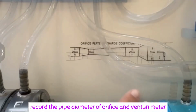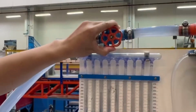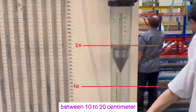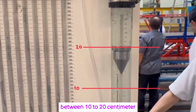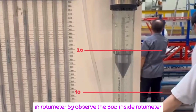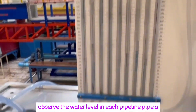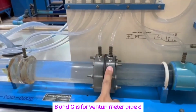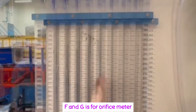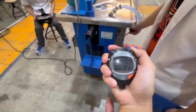Record the pipe diameters of the orifice and venturi meter. Adjust the valve to control the discharge in the range between 10 to 20 cm in the rotameter by observing the bob inside the rotameter. Observe the water level in each pipe line. Pipes A, B, and C are for the venturi meter, pipes D, F, and G are for the orifice meter, and pipes H and I are for the rotameter.